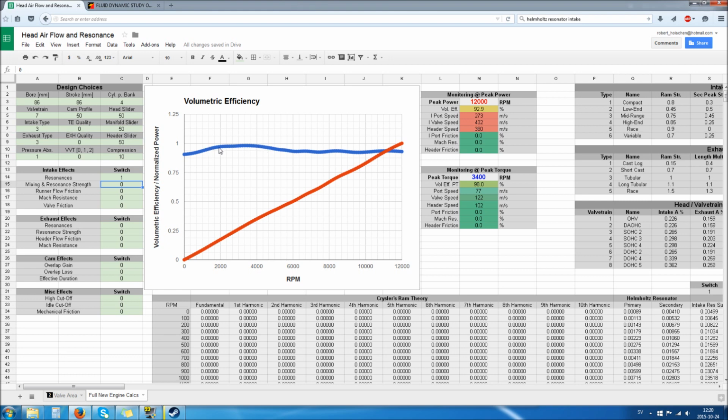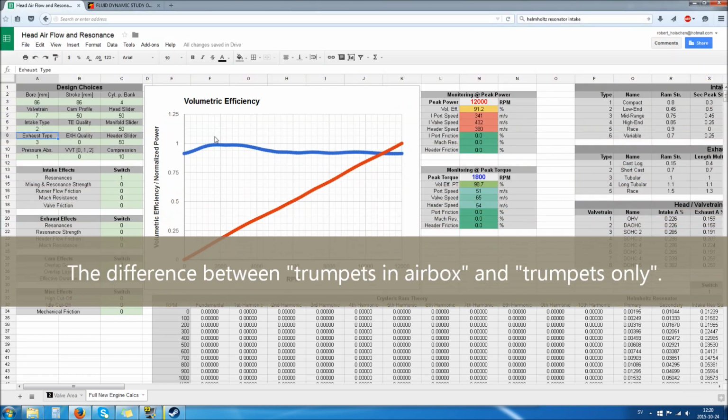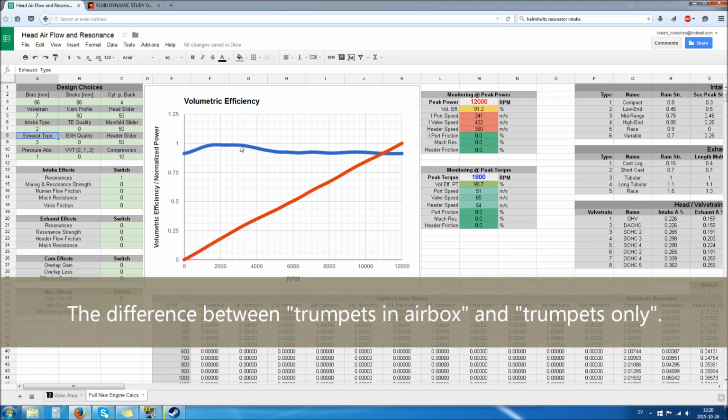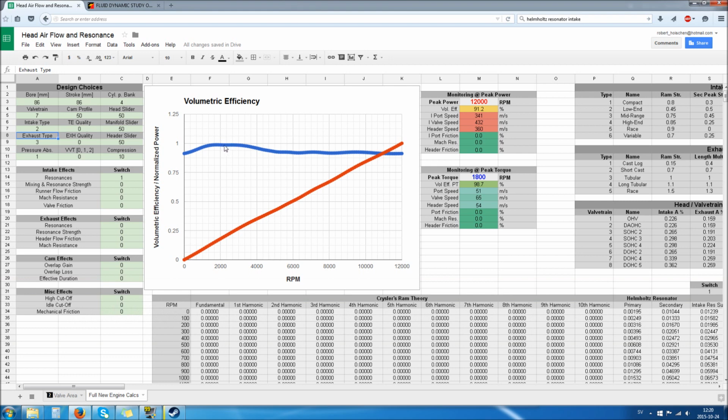And if you only have one, as is the case with intake 5, which is the race intake, there you only get one resonance and then various other resonances which are a different type of resonance. If you go for the eco setup, which has an airbox, like the plenum chamber, you see you get 2 bigger resonances here. Of course, these are both Gaussians, and they are not really separated, as you can see. There's no big drop in here. And so the effect is, instead of having one resonance, if you add a plenum chamber and an additional snorkel on top of that, like the major intake, then you split up the single frequency into 2 frequencies. One which moves slightly higher and the other one which moves down the rev range.